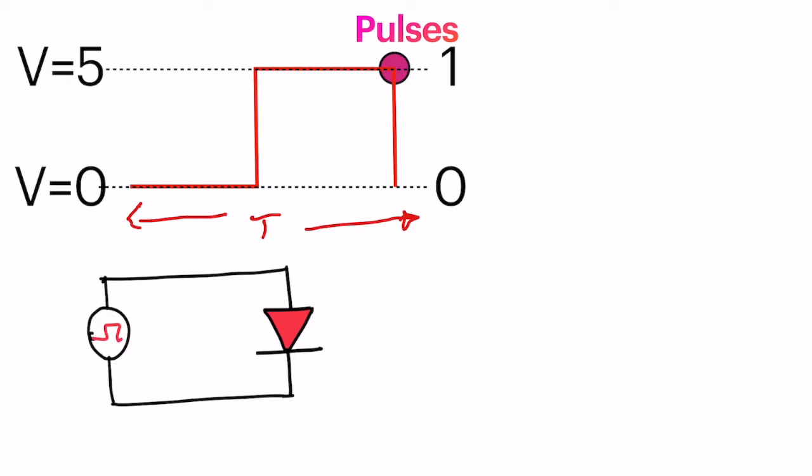Now we know that these pulses can be controlled, and that they will keep continuing along this axis, and this will make the LED go on and off based on whether it is 0 or 1. If the frequency crosses a certain limit, when the flicker rate goes beyond 40 to 50 cycles per second, human eyes will not be able to see the flickering. This is the basic concept used in movies, where you are shown 48 frames per second on the movie screen. This is usually 24 frames, and each frame is repeated twice, so that 48 frames are shown, and your eyes and brain will not be able to distinguish them, and you see them as a continuous sequence. The same thing happens with the LED: when the frequency crosses about 50 or so, you will see continuous light coming from the LED, because we are not able to see the flicker.